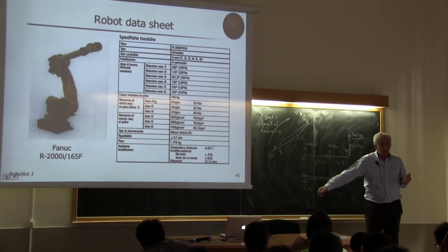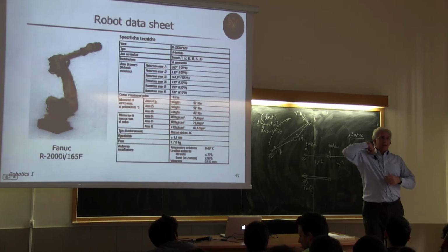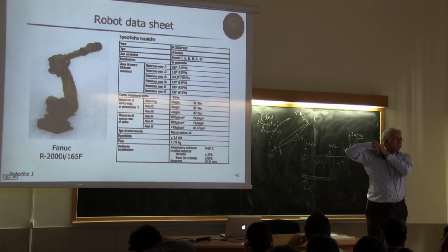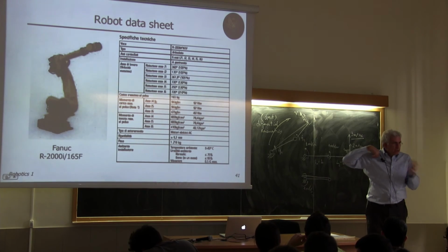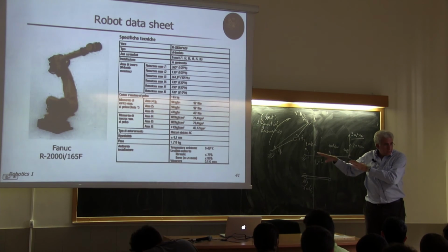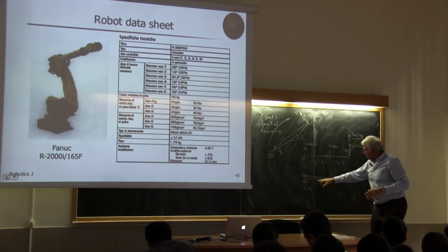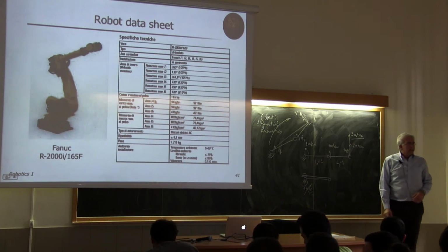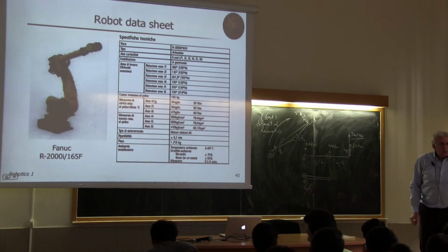No contribution, because I'm folded like this. I'm moving the first joint, but the end effector is not moving. It's changing orientation, but now I'm considering only the linear velocity. Okay? So this, you can put it or you can leave it, will give 0 velocity.